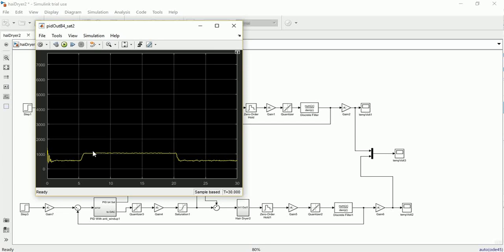It doesn't accumulate, which is good. The integrator keeps on integrating, but there is no accumulation. It's keeping a constant value. And why is it keeping a constant value? Because the input of that integrator is 0. The mechanism forces it to be 0, and therefore it keeps the final value, this value here. And this makes the transient response very good.